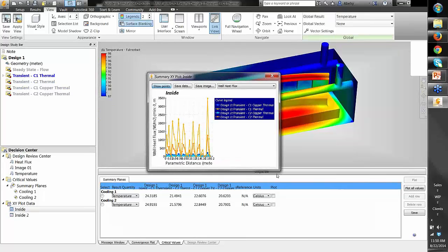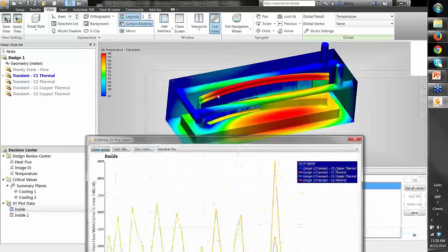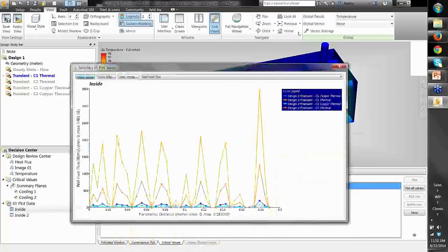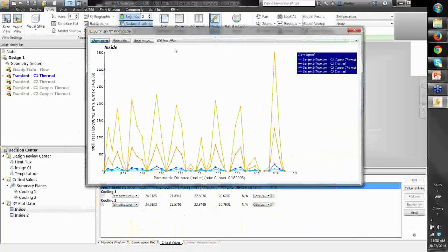So skipping how to show the plots, basically we're just creating a point plot right through all the tips. We have all these loops in here that are designed to pull heat out of the plastic. So this is showing you the rate of how much heat is being pulled out. This is the energy, the watts they're pulling out per area.